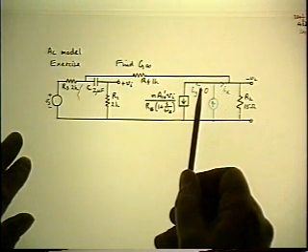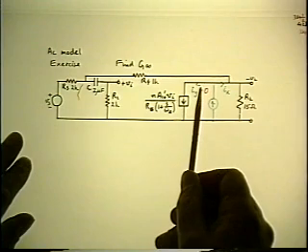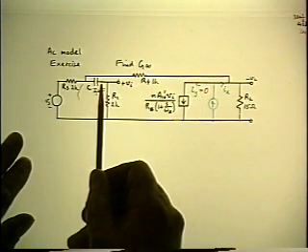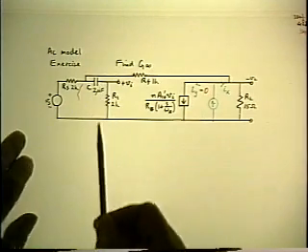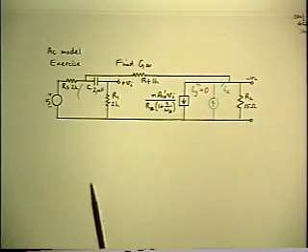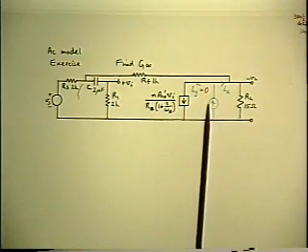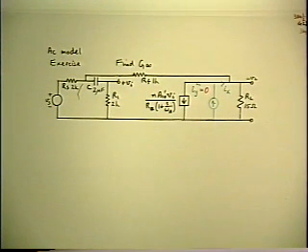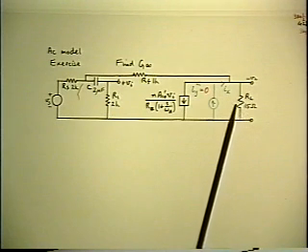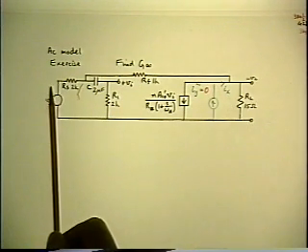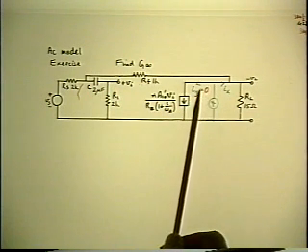And the reason we choose to do that is that if you null the IY, it propagates back to the input and nulls the error signal. And we know from the original definition that the nulled error signal is the condition under which we get the ideal closed loop gain g infinity, because it simulates infinite loop gain. So that's all you have to do. And here's your chance to practice doing a null double injection calculation again. What is it you want to find out? You want to find VL over VS under the condition that IY is nulled.